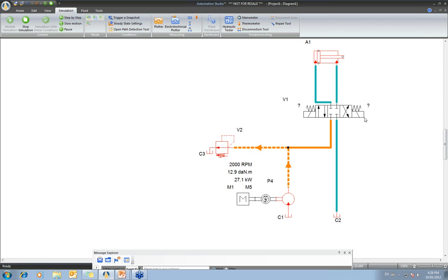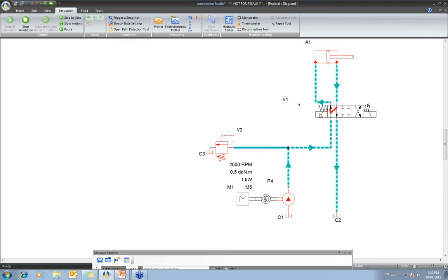One of them is to shift the valve. So if you had a lever over here, you'd be able to shift the valve. You can also click directly on the directional valve. So you'll be able to shift the valve by forcing the spool position to simulate. If you want to release that force state, you simply have to click on one of the commands that you have on the side. It could be either a spring or the solenoid. It's whatever you want, okay?